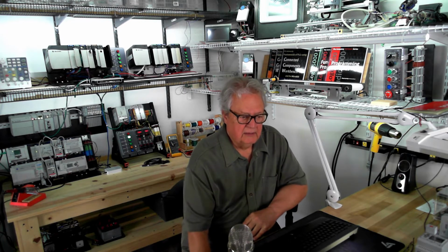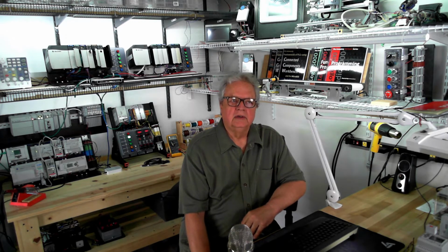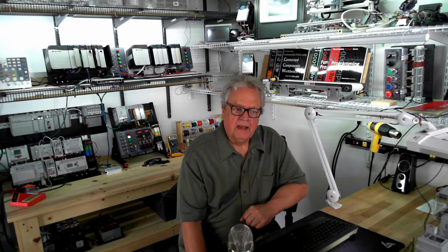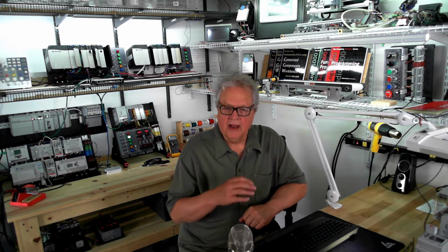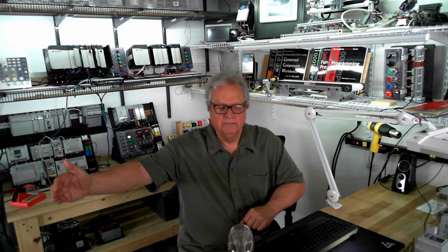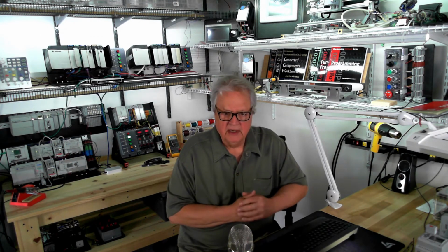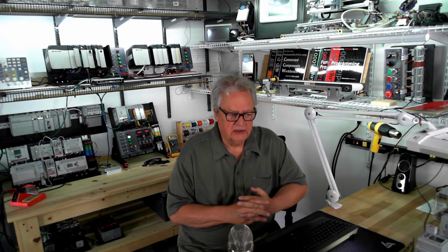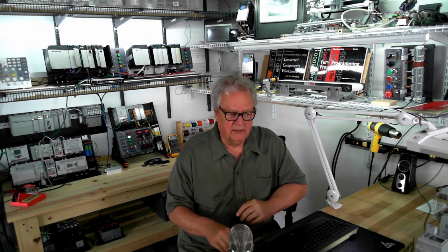And typically, that's what we would use for occupancy on a conveyor. As a carton or an object goes onto a conveyor, we count up, and when it goes off the other end, we count down. So this is really not a big lab project. So let's just get right into it. Count up, count down, and count up down.